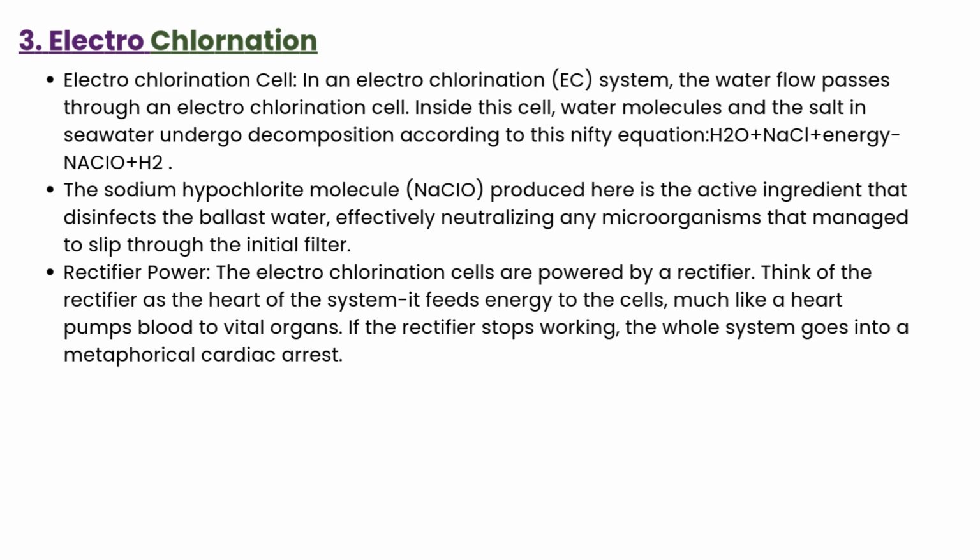The sodium hypochlorite molecule produced here is the active ingredient that disinfects the ballast water, effectively neutralizing any microorganism that manages to slip through the initial filter. Now, this sodium hypochlorite molecule which is produced, that is the one which is disinfecting.